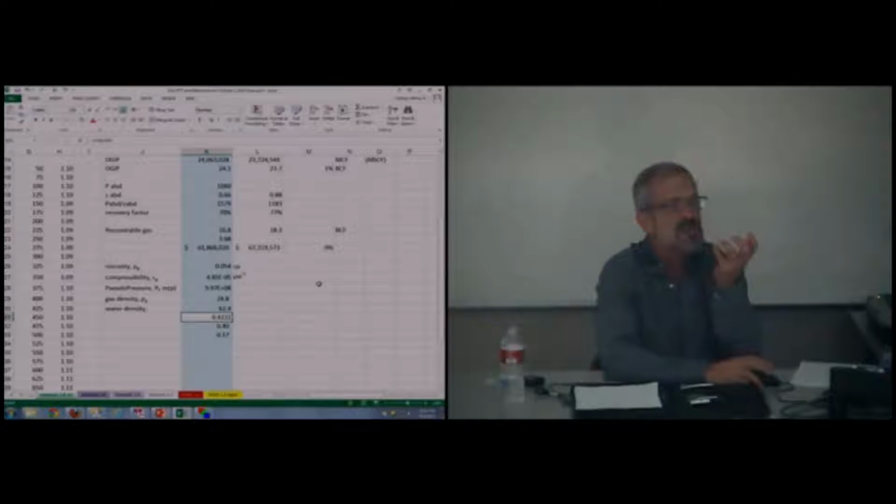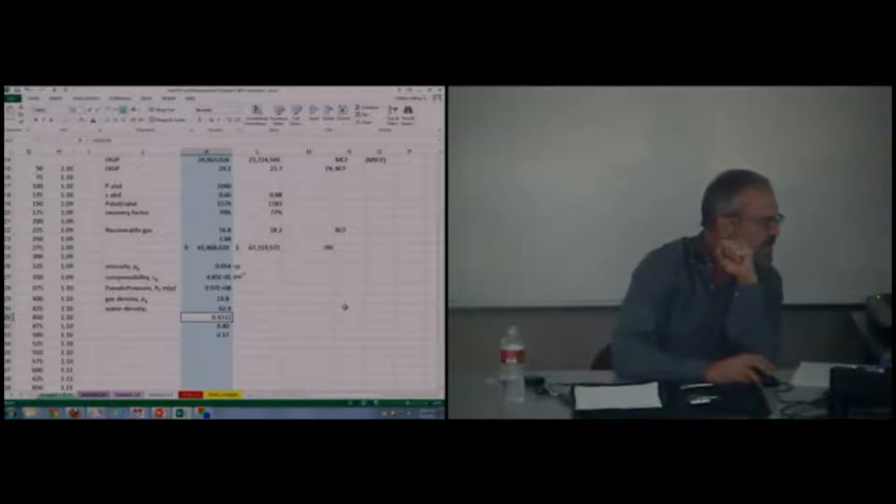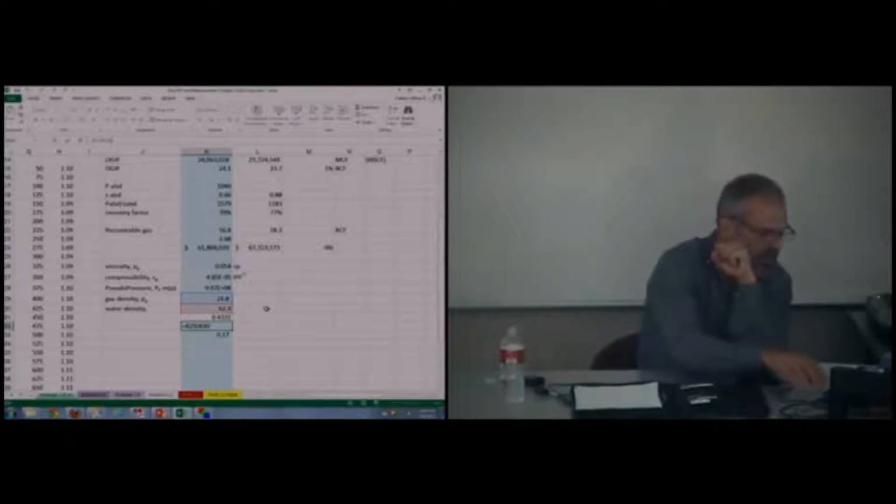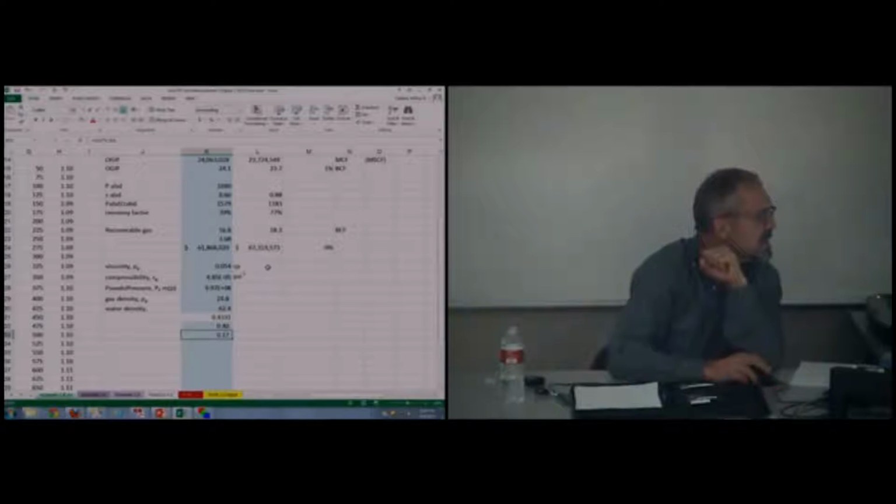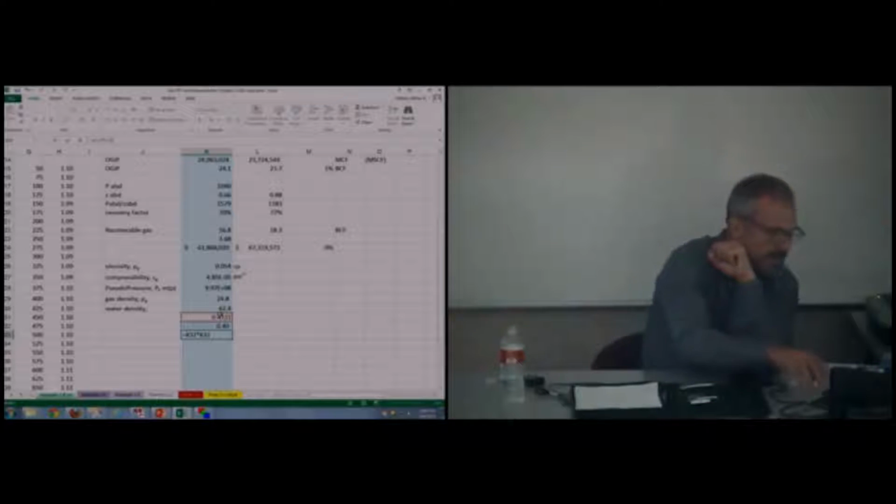So that's just a units conversion from density to gradient. Density to gradient is just a division by 12 squared. Instead of pounds per cubic foot, it's pounds per square inch per linear foot. So now I've converted that, and then I want to multiply it by my more accurate number now.